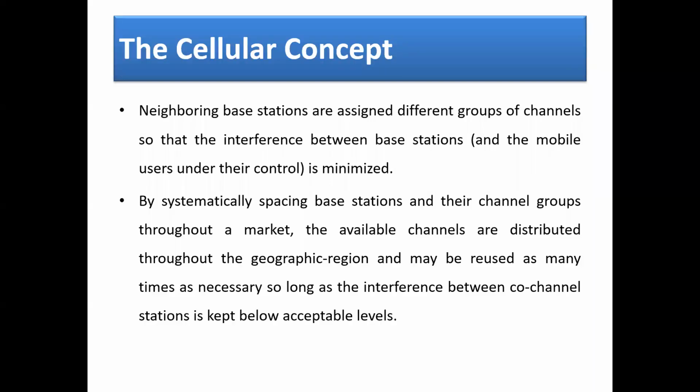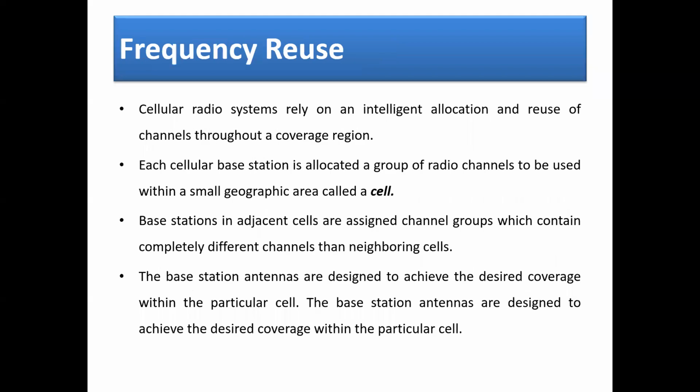Yes, neighboring base stations, as I have told you, are assigned different groups of channels so that the interference between base stations and the mobile users under their control is minimized. By symmetrically spacing base stations and their channel groups throughout the market, the available channels are distributed throughout the geographic region and may be used as many times as necessary. But we have to keep in our mind the level of the interference must be kept at acceptable level.